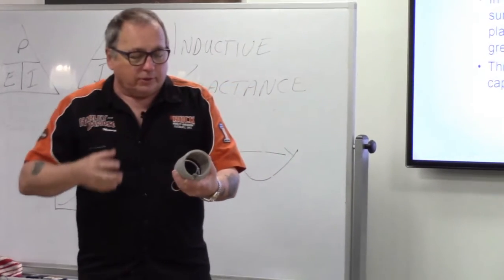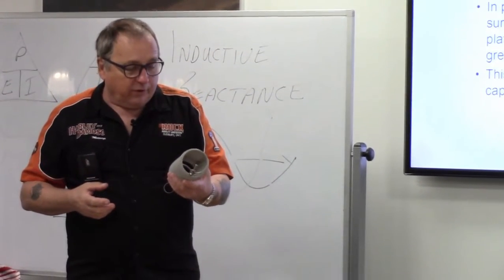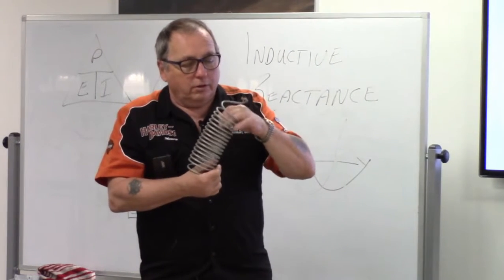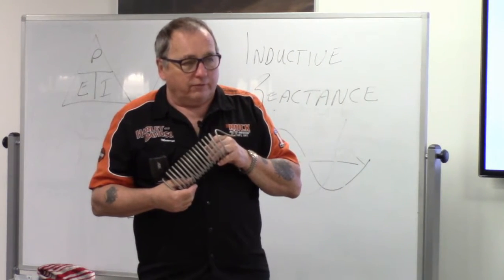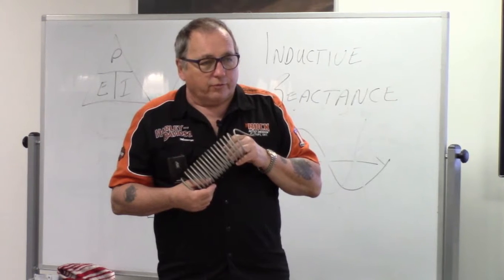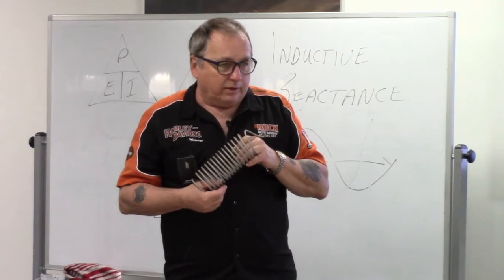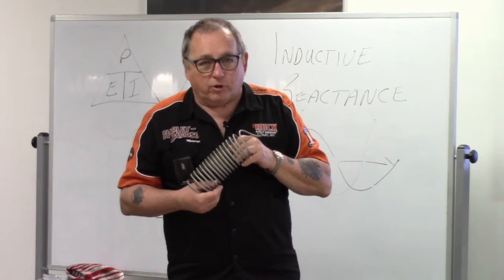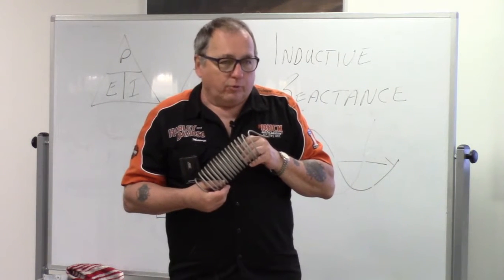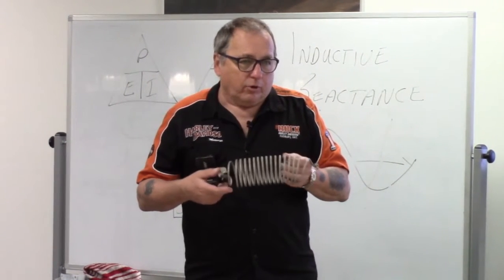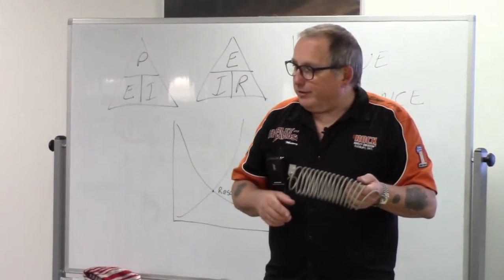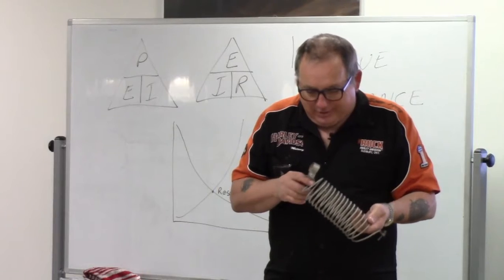That's what I meant. That's one thing I forgot. The number of turns on a coil determines the strength of the magnetic field. The amount of current through that coil determines the strength of the magnetic field. So if you want to make the field stronger, you can put more turns or you can put more current. In order to put more current, you need more voltage. Bigger wire. This is pretty big wire.